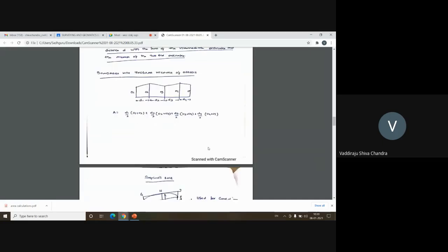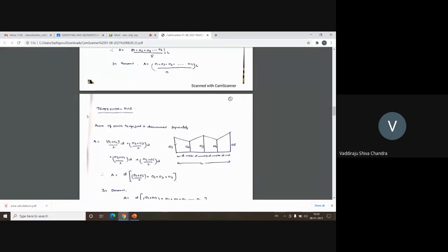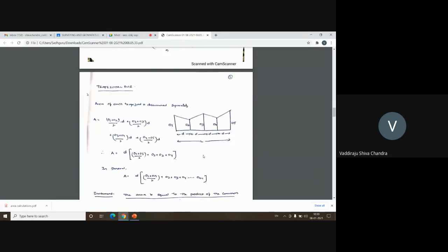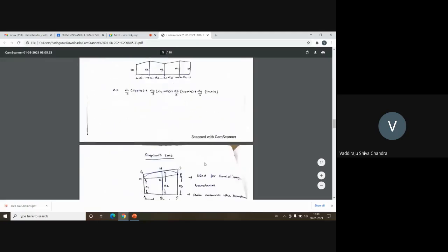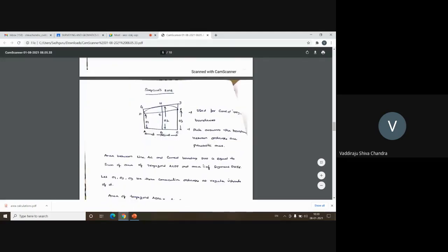Okay. So the assumption in this trapezoidal method is that the two ordinates are joined with a straight line. But as I said earlier, there can't be perfectly straight boundaries on the ground, on the earth's surface, or in agricultural fields especially. So the values you get may not be 100% accurate. In order to counteract that and improve the accuracy of the area calculations, we have one more rule, called Simpson's rule, where we consider the curvature of the boundaries.